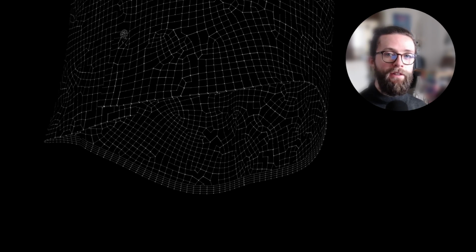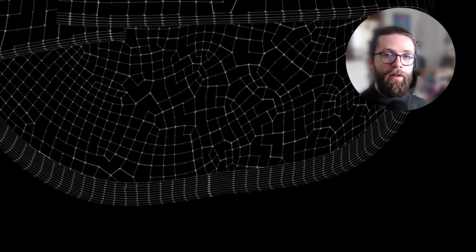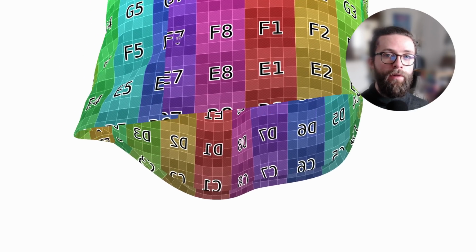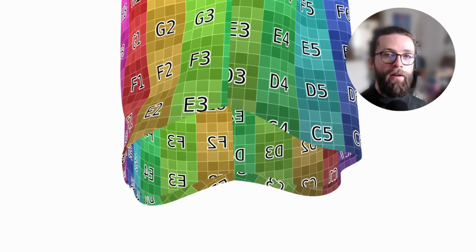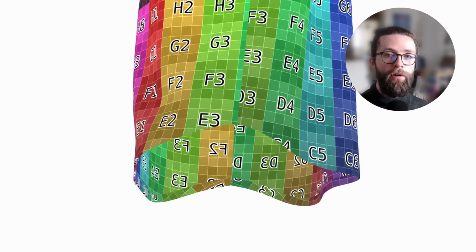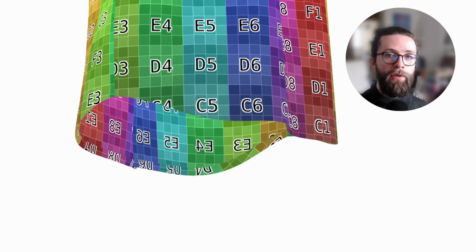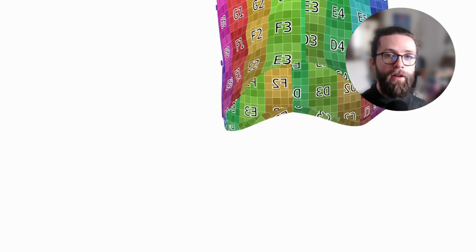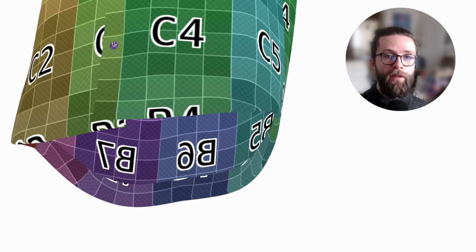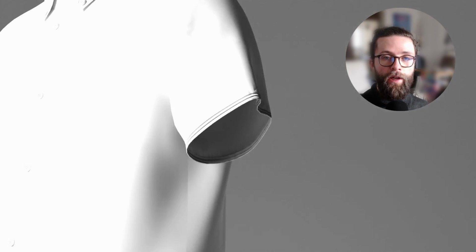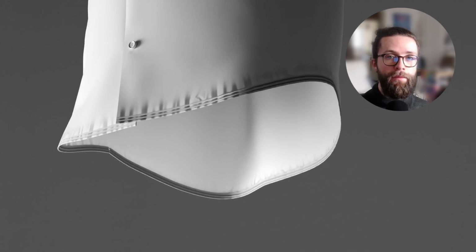The answer is yes, and it works surprisingly well with any kind of animation as long as you have a properly UV unwrapped model. Working in UV space, which is always stable, we can create geometry on top of the usual modifier stack, and we can dial every aspect of it, as well as create custom UV space for seam puckering shading and precise effect near the seams.